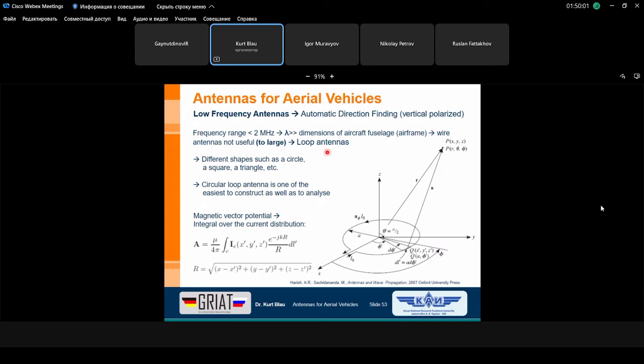If we have a low radiation resistance on the antenna side, and we have, let's say, an input resistance of our receiver, then we have a very large mismatch ratio. It means a lot of our signal is more or less attenuated by this large difference in radiation resistance and receiver input resistance. These two values should be more or less near each other, but should not have a high difference.